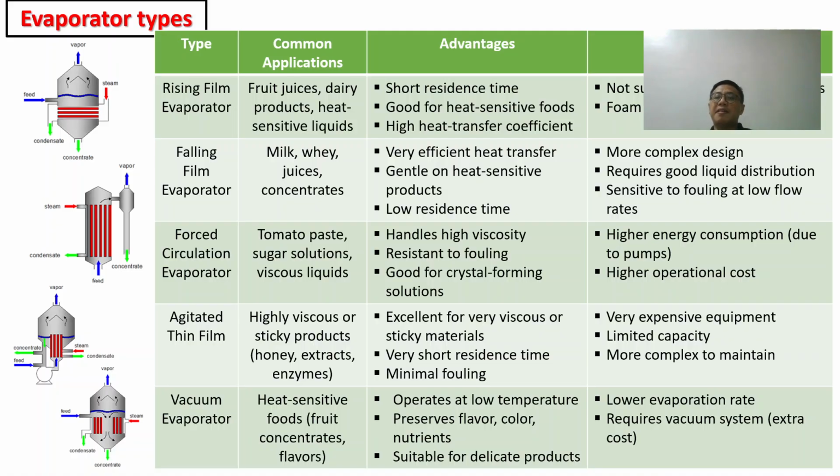Okay, and its disadvantages are a low evaporation rate. Because of the vacuum environment, the evaporation rate may decrease. And the system to create vacuum inside the evaporator is expensive. The vacuum pump is very expensive, and the operation of the vacuum pump is expensive. So the whole design also requires a very special design. We have to ensure it's very enclosed.